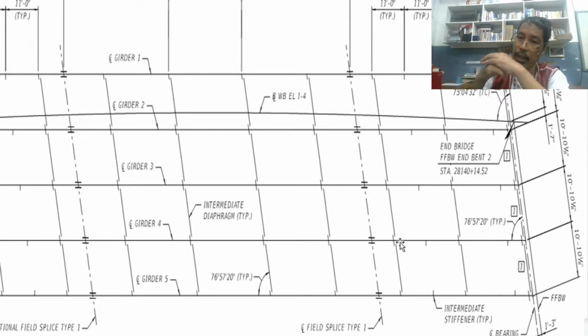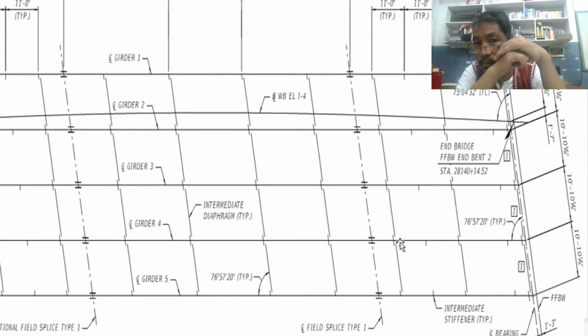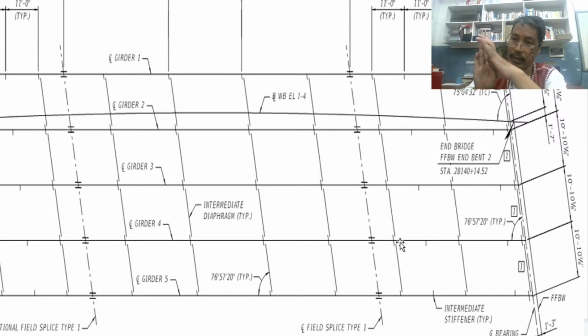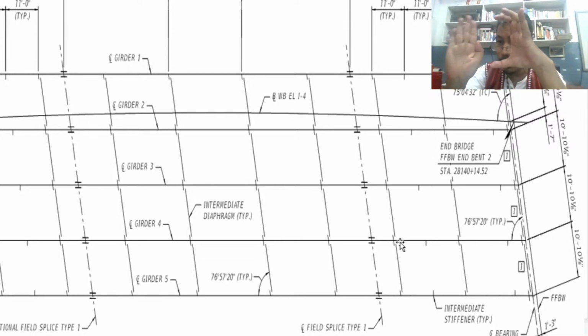So meaning at the middle of diaphragm, we have to make a stiffener. They are not diaphragm, but they are stiffener. It stiffens the web of the W-type beam. Okay? So, are we following? We know what is W-type. We know what is beam. We know what to expect about flange and web. So we are stiffening the web by putting a plate of metal that way.